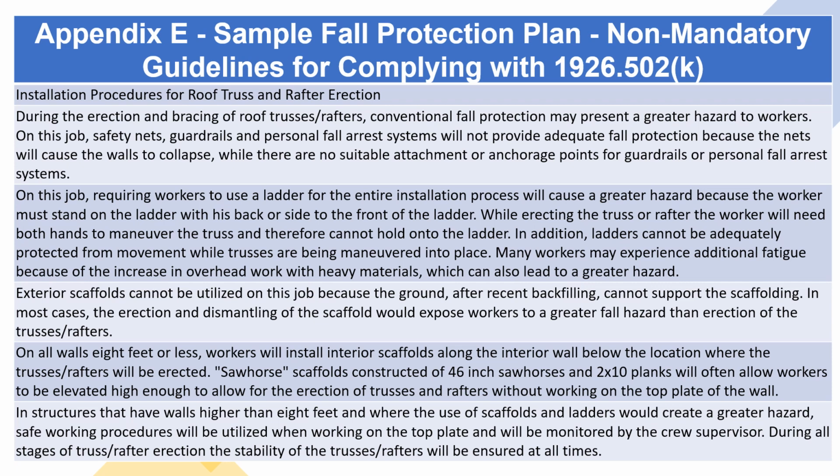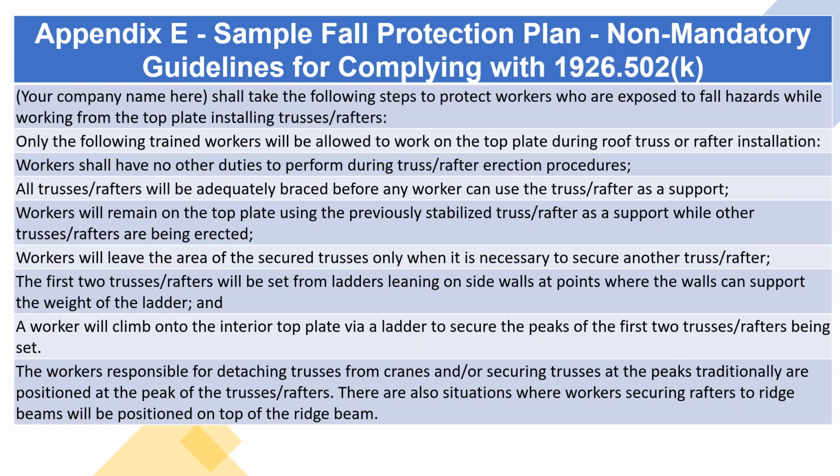In structures that have walls higher than 8 feet and where the use of scaffolds and ladders would create a greater hazard, safe working procedures will be utilized when working on the top plate and will be monitored by the crew supervisor. During all stages of truss/rafter erection, the stability of the trusses/rafters will be ensured at all times. Your company name here shall take the following steps to protect workers who are exposed to fall hazards while working from the top plate installing trusses/rafters.